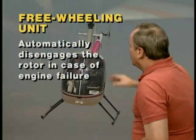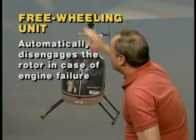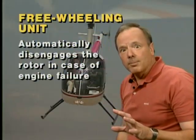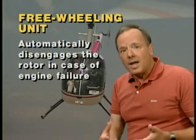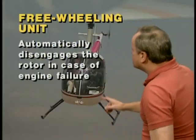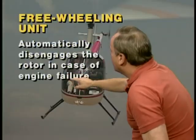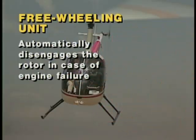The purpose of it is to allow you to be able to fly the aircraft in the event of an engine failure and to keep the rotor RPM up. Now, they'll also say so you can practice autorotations. Well, it's true, you can practice autorotations, but that's not the purpose of it. The purpose of it is to disengage the rotor in the event of, and terrible thought, an engine failure.